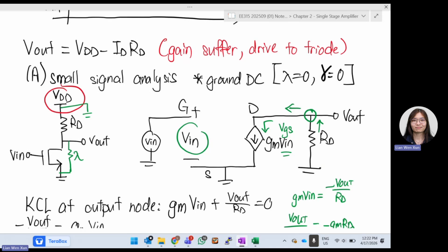So first, we already got this black color. You see the black color part only of this circuit. This is our basic common source with resistive load. So first, we can start with drawing the transistor. If you don't see any point, we draw the transistor only. Okay, so we have our VG. We say transistor, we got a gate, drain at the same line, source at the bottom, and then there's one GM. We say this is GM VGS.